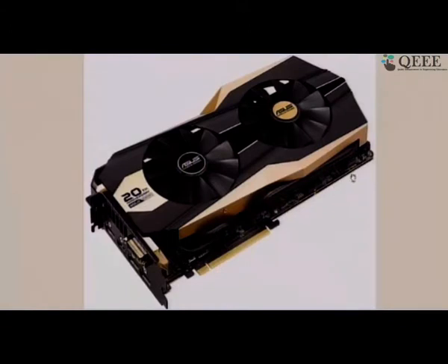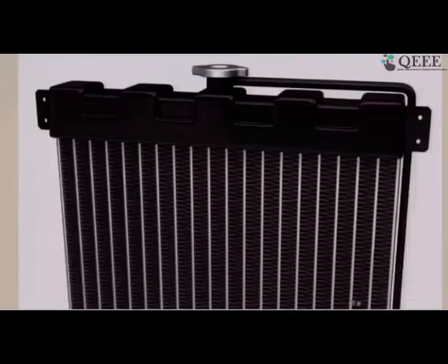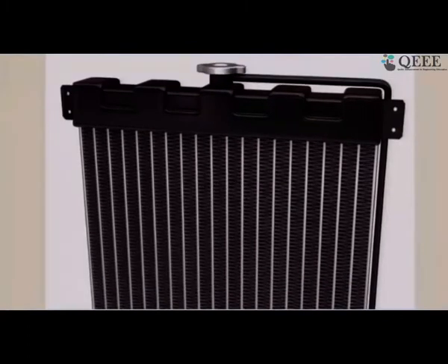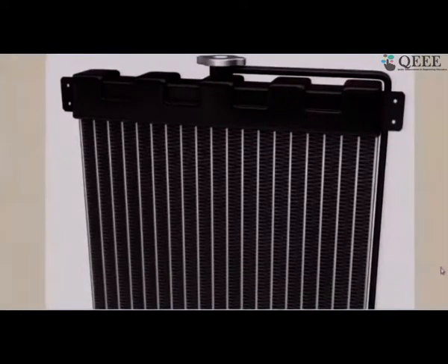But what you see on this is that the load, the card, which has chips on it, is at the bottom, and on top of that, in this small thing, there are two fans. Because the GPU is generating so much heat that we need to then take that heat out to keep the chips within a certain temperature limit. So again, here you have how fast you can drive graphics, how fast depends on how fast you can cool it. So again, this is a picture of the radiator we were talking of. That was a sketch. This is an actual radiator, and we continuously want to make it better and better, more and more compact, and of course less and less expensive.